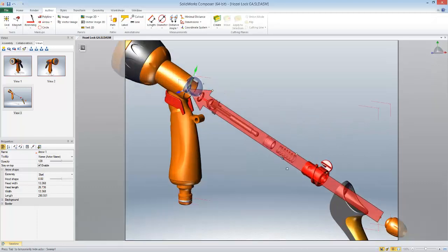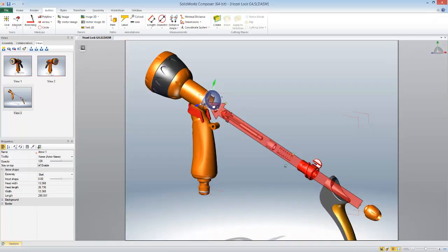And so the arrow at the moment is pointing that way. Now actually if I want to say disassemble in this order, I want the arrow to go the other way, so not a problem. What I can do is select the arrow, and then down here you get the properties for whatever you click on in Composer. For this arrow, I can tell it to put the arrowhead at the other end, like so.